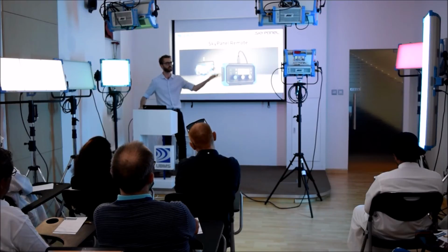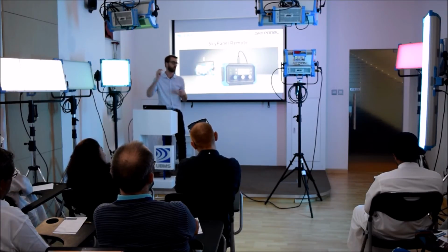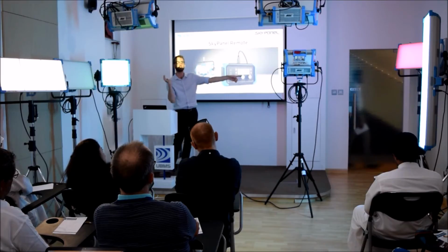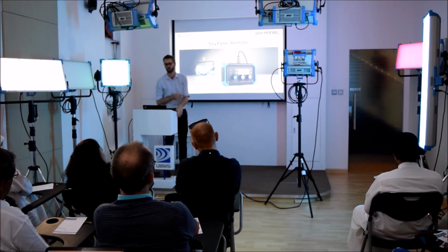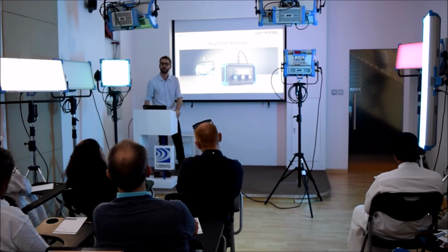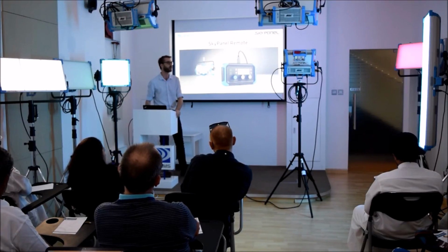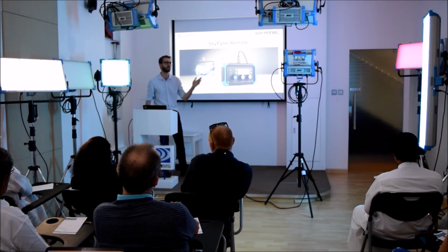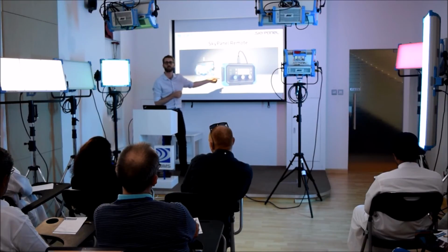So if you had 6 lights and they were all connected by a DMX cable, and you had this controller on your master and the others were slaves to it, then you'd have control over all 6 lights from one of these controllers. All of them? Only one? Well, no, you'd have control over multiple lights if they're in slave master mode, and if this one is connected to the master.